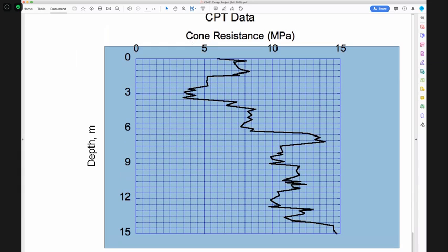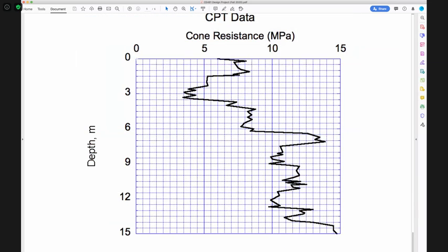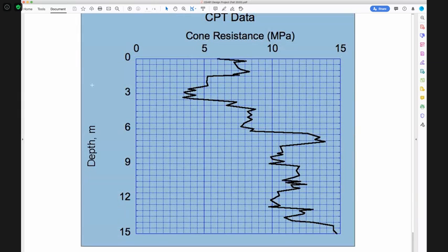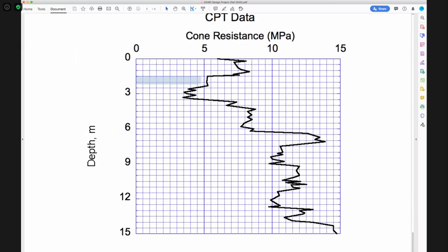And just as an example, I'll say something like this might apply. That would be a reasonable estimation for that layer. We're a little overshooting it here, we're a little undershooting it here, and saying this whole layer is about the same strength. And then you'd come back and get something like the next one. You'll see this in the Schmertmann technique, but you know, the next layer might be something like this, and so on. But it's your judgment on this, how refined you want to get.